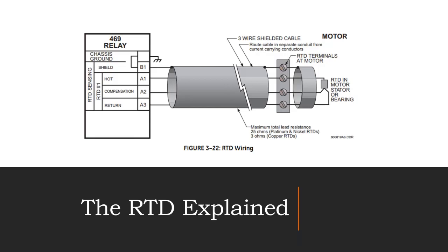All right, what you've got on this RTD, if you notice, there are 3 wires to it. I've got a wire connected to A1, A2, and A3. What we want to know is the resistance in the RTD. But the issue is we also have resistance in the wire, so we need to compensate.